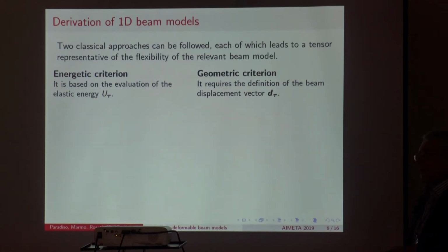I mean, both in terms of energy and in terms of geometric quantities, in the 1D model and in the Saint-Venant model, you will get the same solution. This does not hold for the shear stresses. And that's why in the literature, you find two different approaches that reflect in the definition of the so-called shear correction factors.